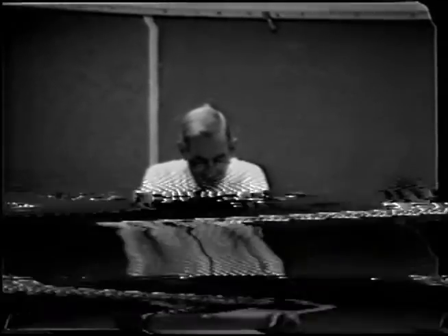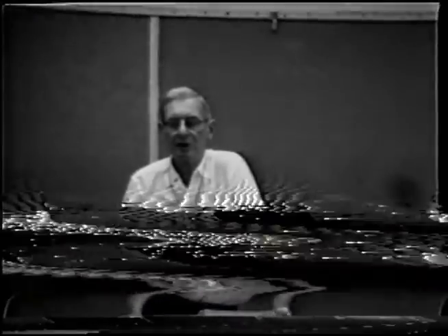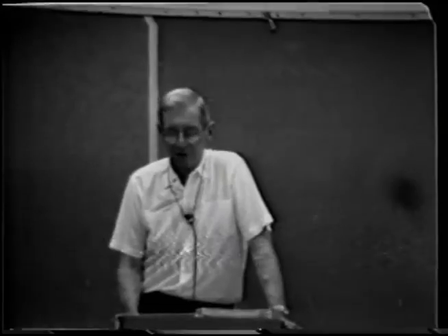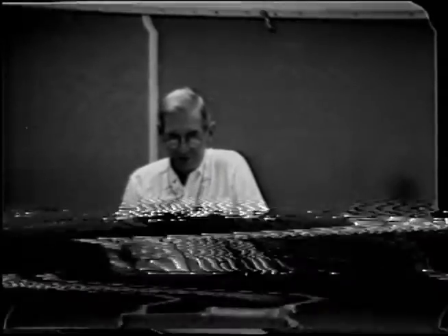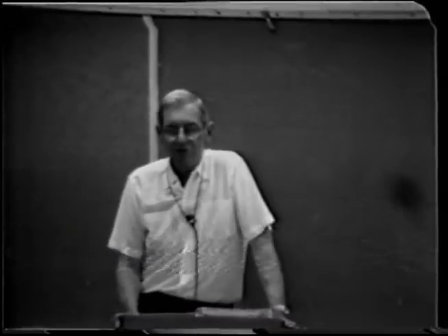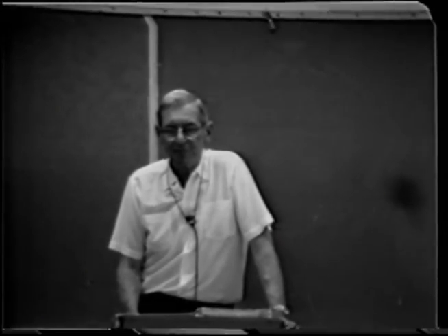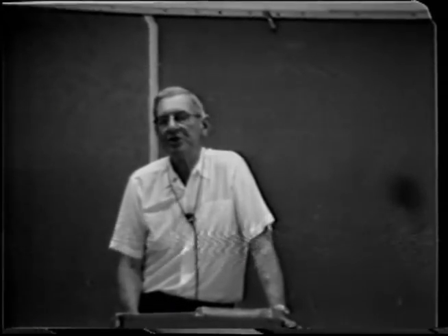Sterile filtration is another method. And that, of course, impairs the quality the least of the three methods we discussed so far, provided that you take pains that you do not unduly aerate the wine during the sterile filtration. But sterile filtration requires very painstaking attention to all the details.